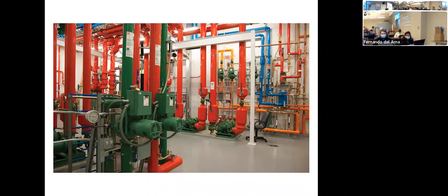So in these mechanical rooms, sometimes you find two parallel water pumps. This is because we can stop the circulation of this water, and then we have just a backup. If this stops working, the other one starts working immediately, and then you have to repair this one, because those pumps don't last forever.